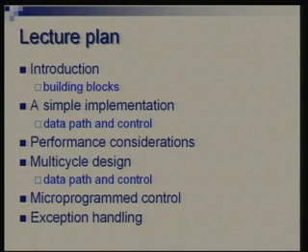So, data path is the one which is doing the computation, and control is the one which guides or directs these computations so that the right action takes place at the right time. This is part of the overall plan. We are looking at a simple implementation where the entire instruction gets executed in a single cycle. After we finish with this, we will look at the performance considerations and probably go for a more involved design, which is a multi-cycle design.